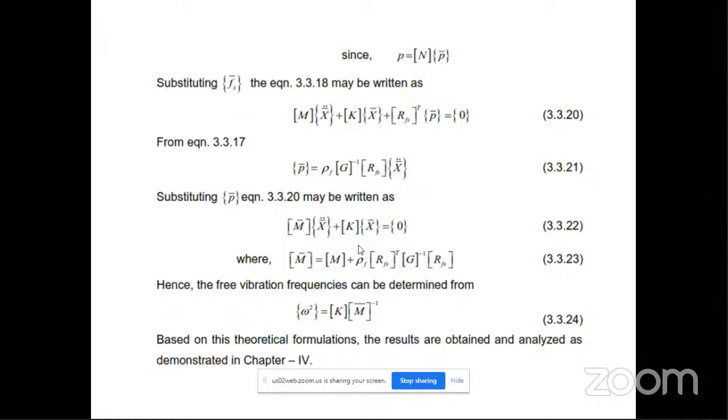Though the liquid may be gasoline or any other chemical, it is incompressible for a general force, but when an earthquake occurs, then the little compressibility will have a disastrous effect. So I have to consider the compressibility of the fluid. But for the beginning, I have considered the fluid to be incompressible, non-viscous.